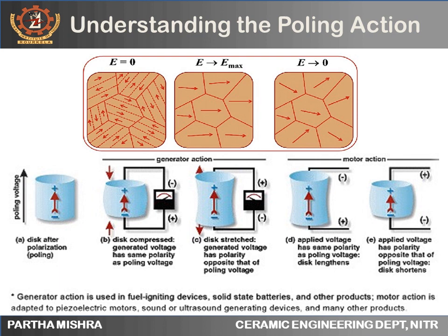But if we pass an electric field or apply a voltage along with crossing the Curie temperature, it would force these unpoled or unpolarized dipoles to align in the direction of the electric field. And now the polarization in the material will stay the same even when the electric field is switched off. This action is called electric poling.